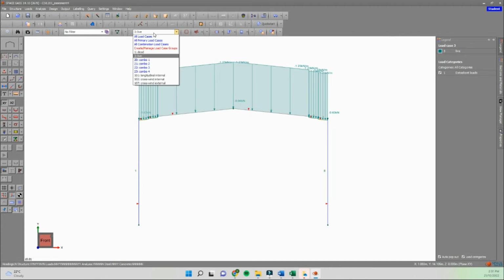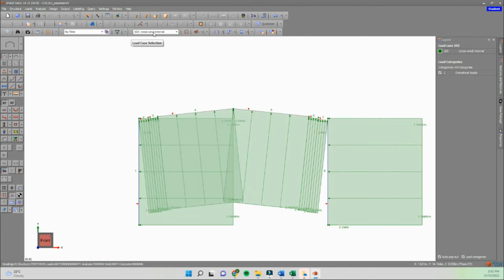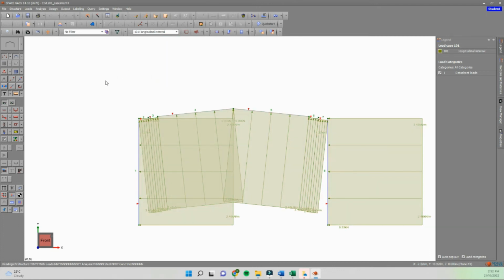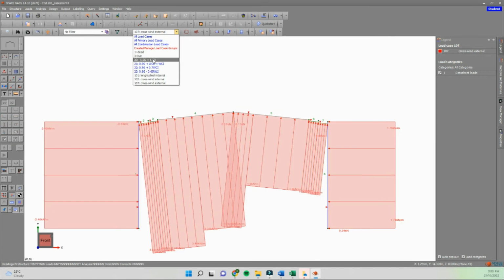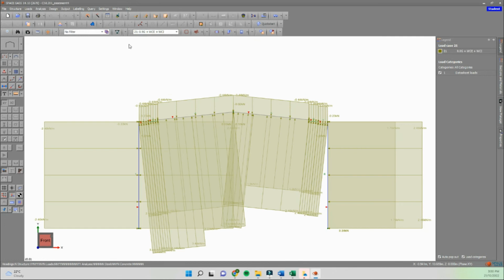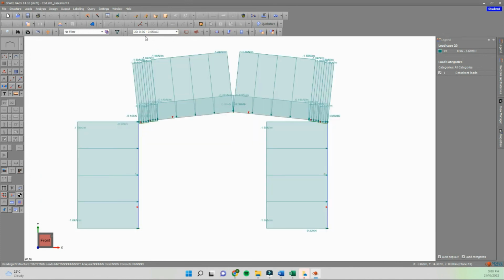the uses of the building; internal crosswind, WCI, which refers to the wind factor affecting the structure's side from the inside, as opposed to external crosswind, WCE, that affects it from the outside. Internal longitudinal wind, WLI, affects the structure in the length direction of the structure, which is into the page looking at the 2D model. These loads could be combined with short-term and long-term combination factors to find desired limit states, as you can see on screen. The loads are also used in further limit states tests in accordance with the current Australian Standards 1170. By applying this analysis, the team receives a detailed evaluation of the limits of our build.